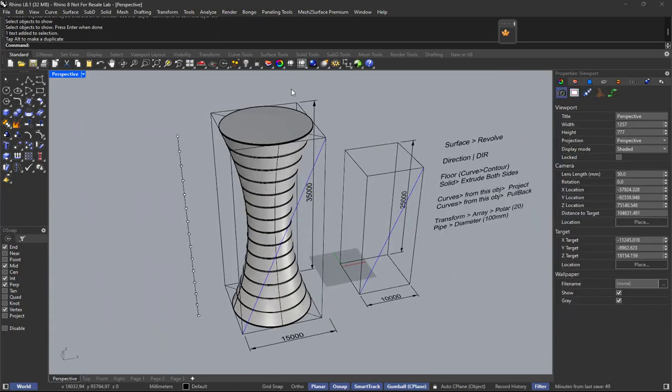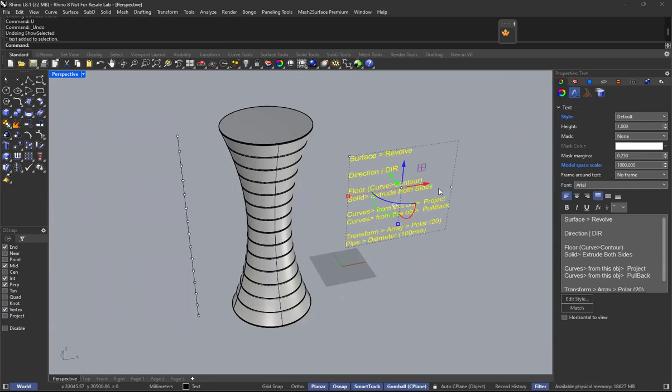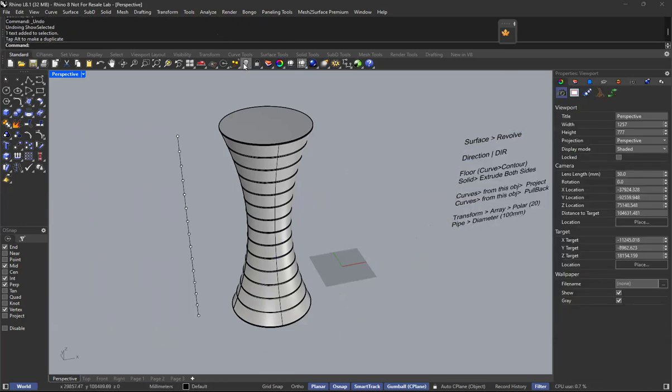I seldom talk about the hide and show command. Maybe I will do that again. For this instance, there is a nice command. Sometimes during class we're moving quite fast and I may miss out some commands that are useful as well. If you notice, there is a center mouse icon, beg your pardon, an icon that reflects a light bulb. What it does is you are transported to a hidden space to select items that you want to turn on. So this is a very useful tool.